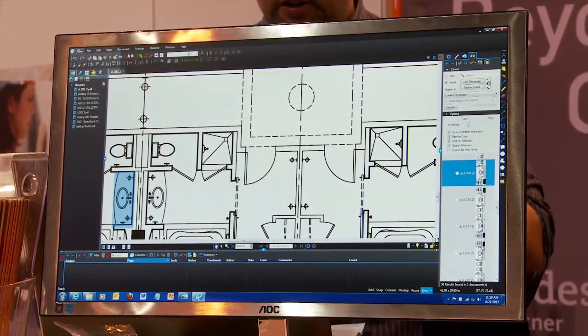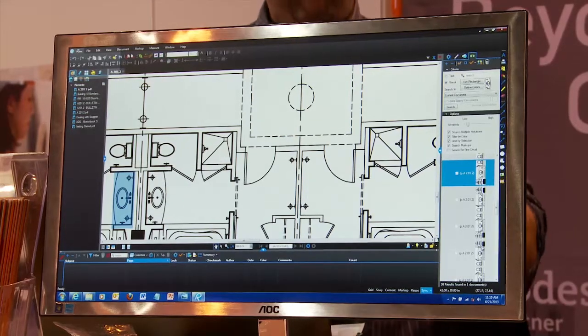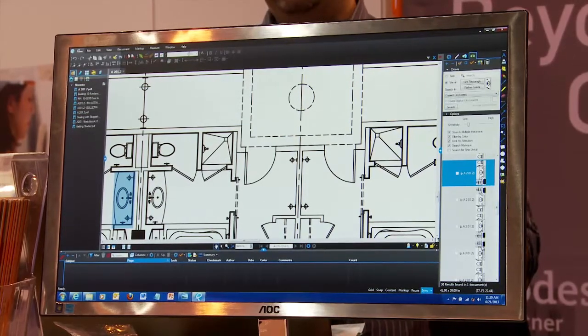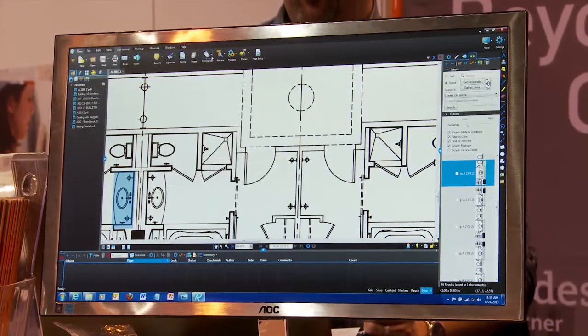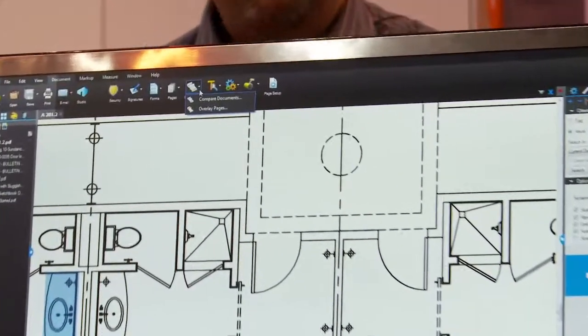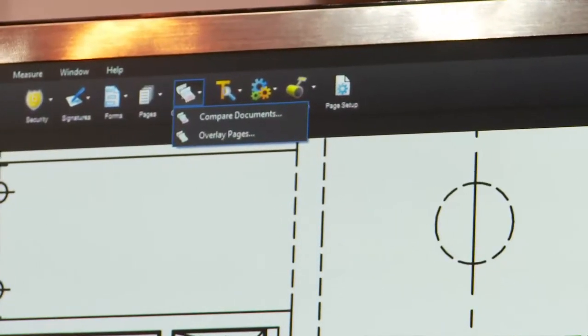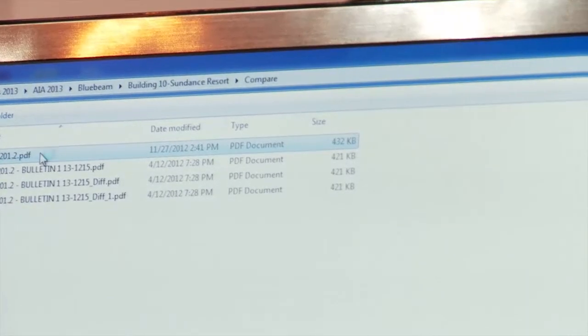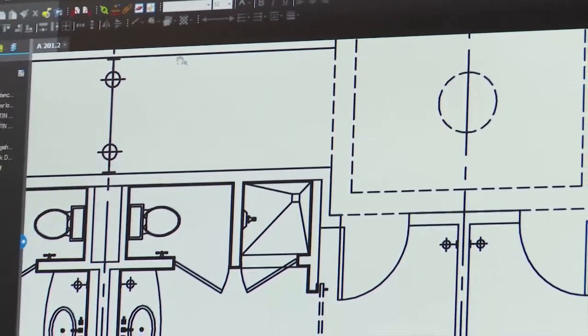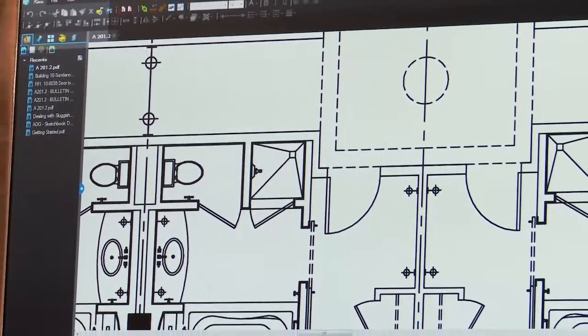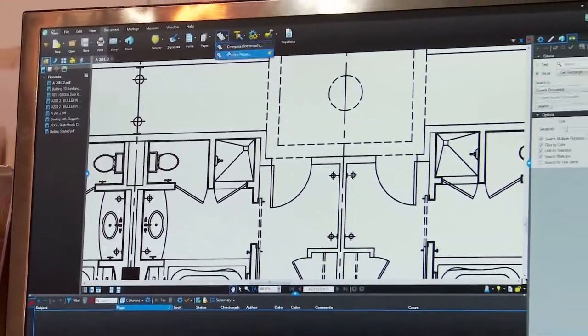But just to conclude and just to show you really the beauty of how you can use this for marking up and for tracking change, especially very useful on the construction administration phase on a project, there's a very, very cool feature called comparison. And I think that's the best out of all. What that means is, and let me show you, you could pick one drawing, you can even pick one entire package of drawings that were submitted, and you can do this called compare drawings.